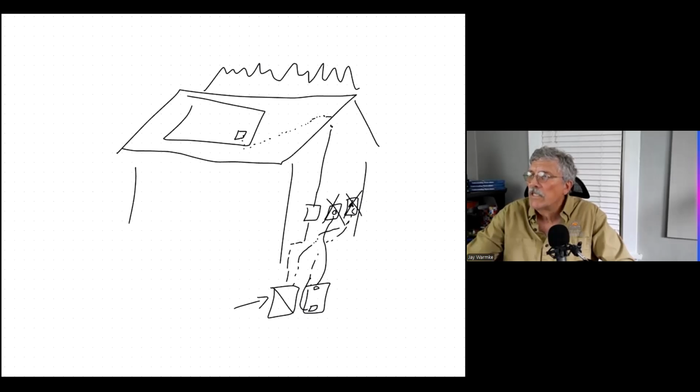But if the sun is shining, these wires going all the way down, they might have turned off the DC disconnect if they thought about it. But if they didn't, these wires all the way to the inverter are still live. And they could be live with as much as 600 volts in a residential setting. So the fireman climbs up onto the roof and he takes out a chainsaw and he starts cutting through the roof to vent the fire, to vent all the smoke out of the building. And he cuts through a 600-volt electric line and it kills him. So that's what they want to avoid.